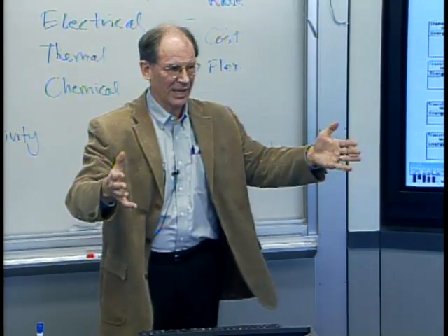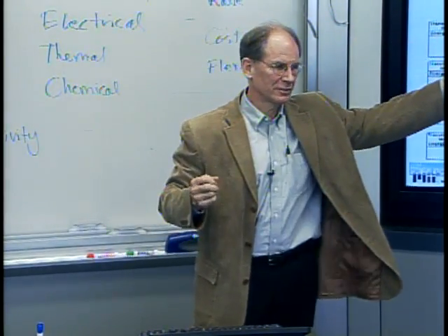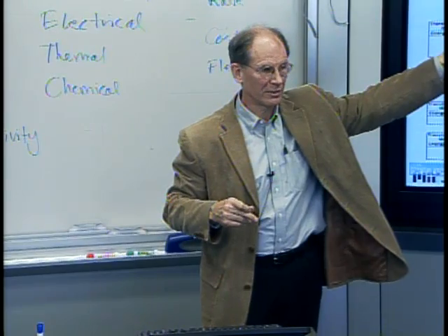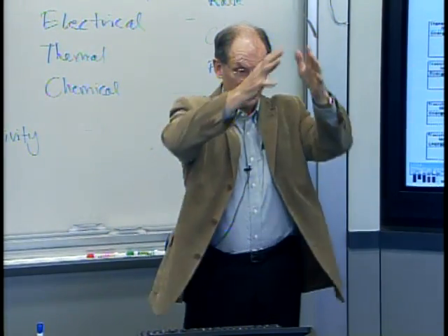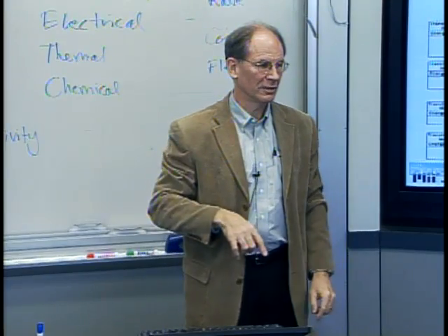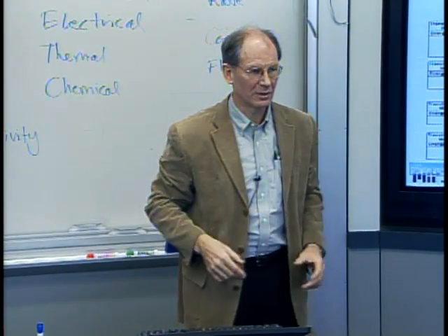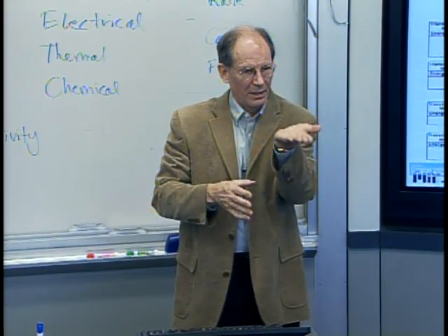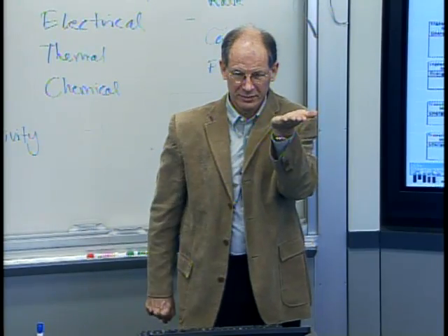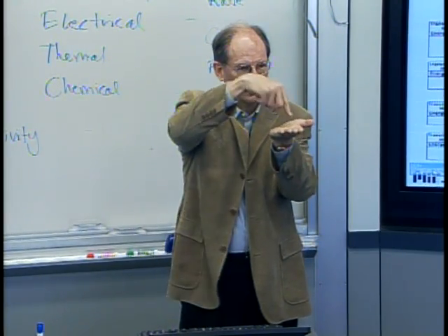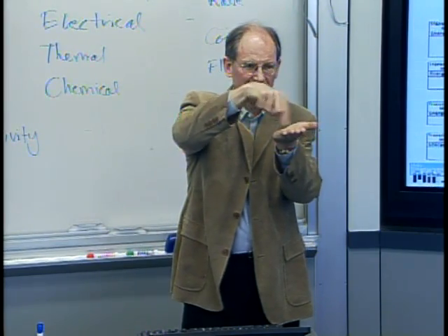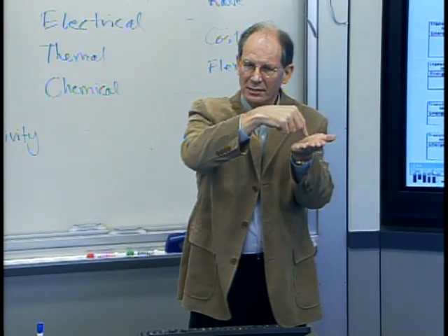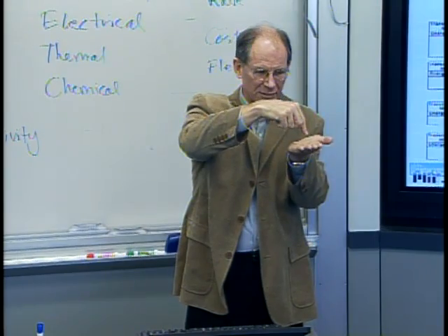So you have this bath. I haven't walked by there this month, but there used to be, in one of these glass-walled classrooms down here at the far end of the 4th floor in the architecture department, this white box with a clear window in it, and it's kind of lit up, and there's usually something going on in there. What you'll see is a bath of nearly colorless liquid with a platen on it. The platen starts at the top with a very thin layer of fluid on it. And this laser, usually not visible, will be dancing across the surface, tracing an outline, and that outline will become solid. Once it's polymerized, it'll move down and do it again.